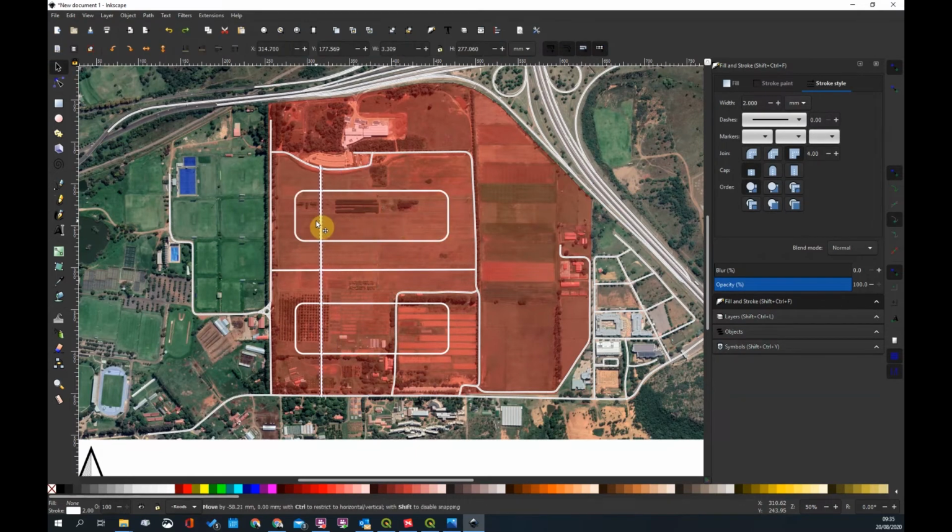Select this line work, Control C, Control V. I'm going to put one there. I'll show you how this will work in a minute. And then Control C, Control V, and put this one over here. So here you can see I'm going to make a bit of a road network where you interconnect here. So you've got some little developments around here, for example. Okay, that works well. All right, so maybe let's just do this first. I can copy these down. Okay. So these 2 bits of line work, I'll adjust them in a minute.